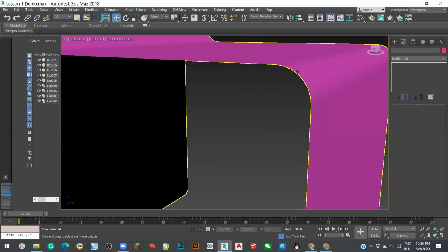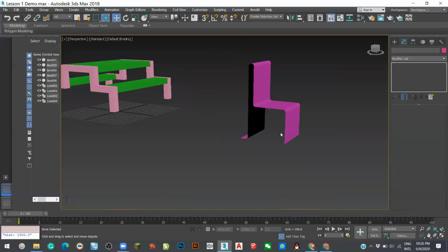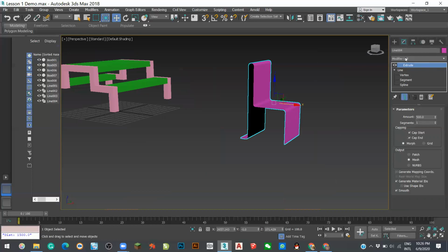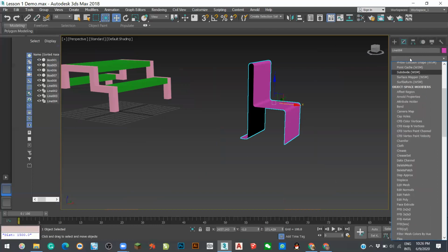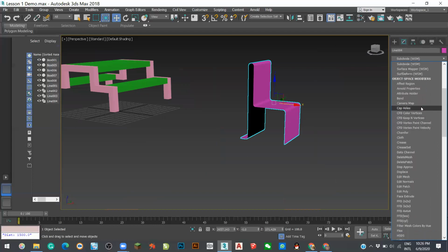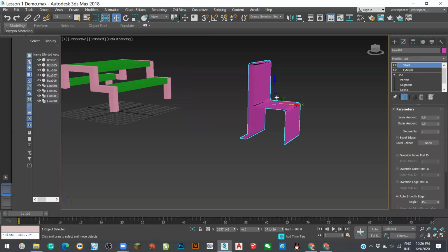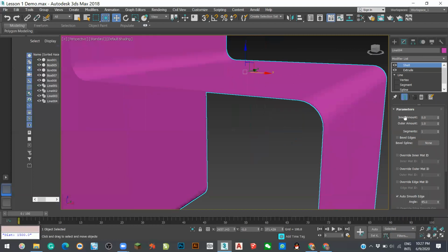But this chair is still very thin, so I will make a thickness for my chair. I will select again, modify, shell. Okay, SHELL. You cannot find it here. Maybe it's below the comma. So I keep pressing S to find the shell. S again. Okay, there will be shell under the selected channel. Click the shell.